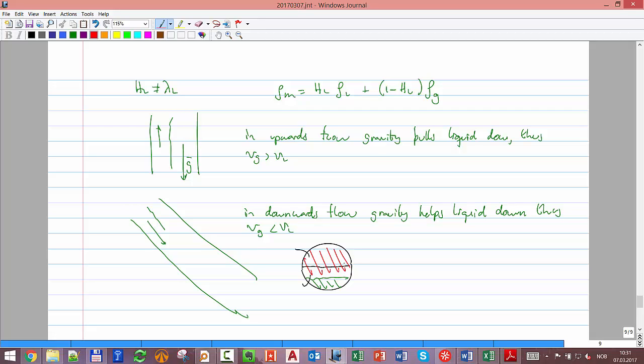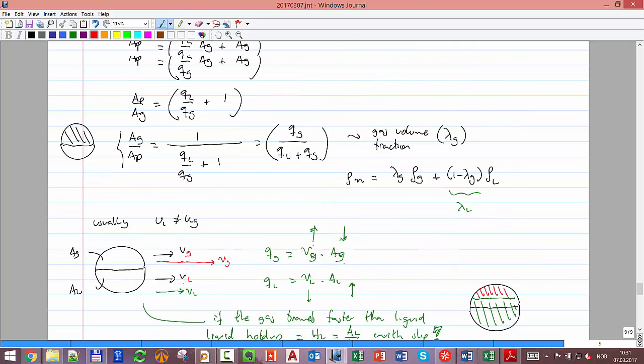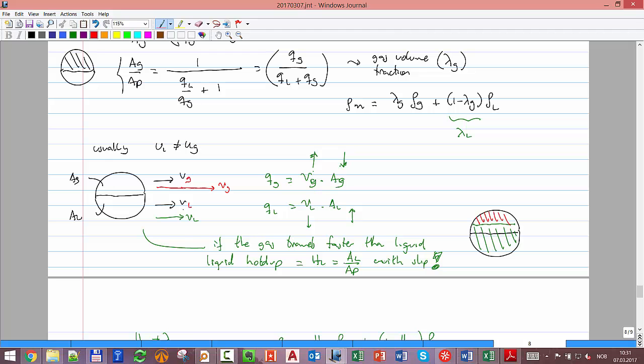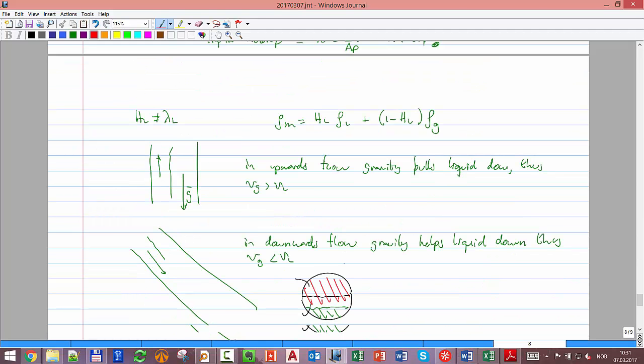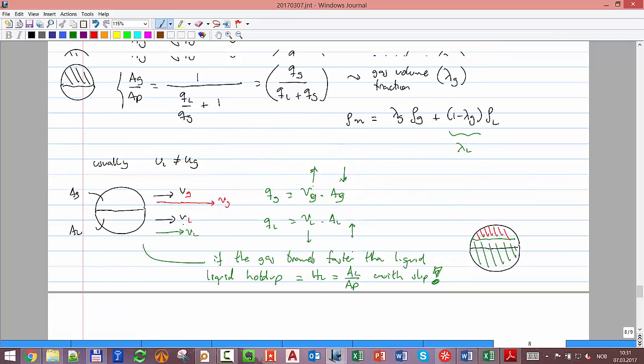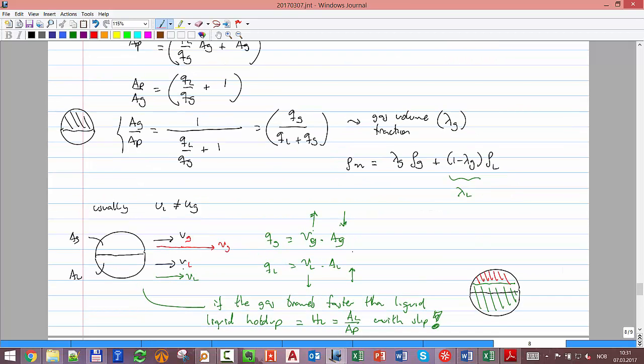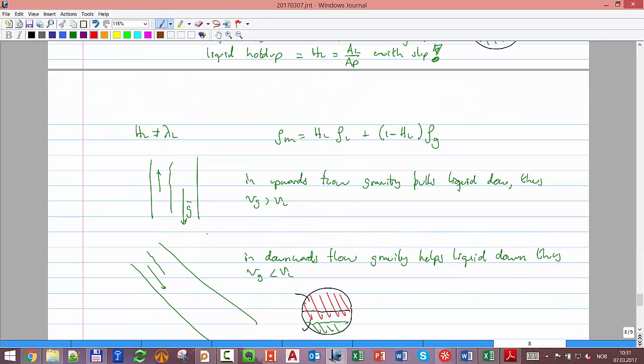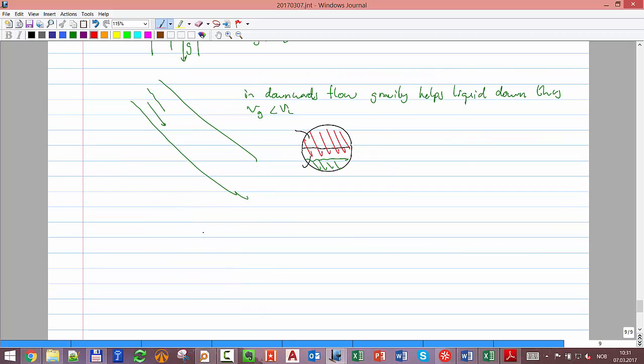The main issue with all of these models is to calculate that holdup, because with the holdup we can calculate the density, and with the density we can do many things. So on top of identifying the flow pattern, we want to have the slip and the density, and they are actually equivalent. I'm not going to show you everything here, not to overload it with equations, but if you have the holdup, you can calculate the real velocities. So how do you calculate the real velocities?